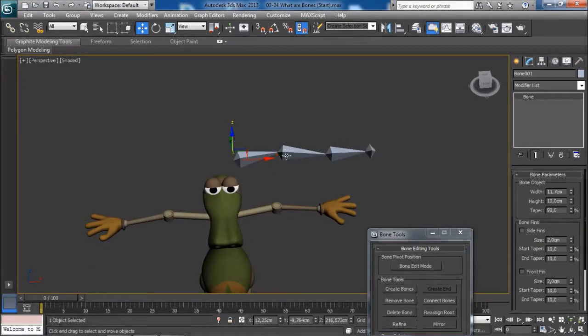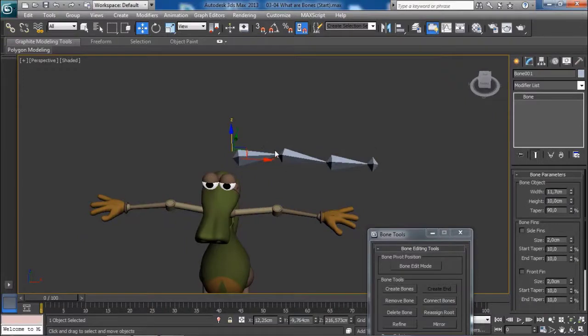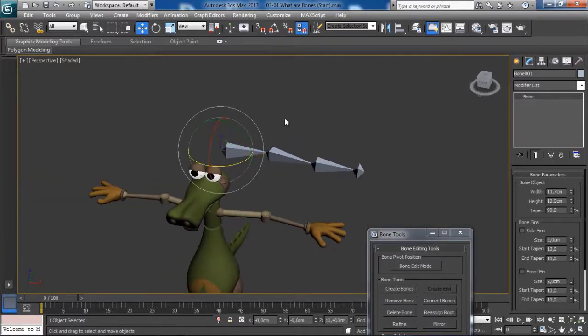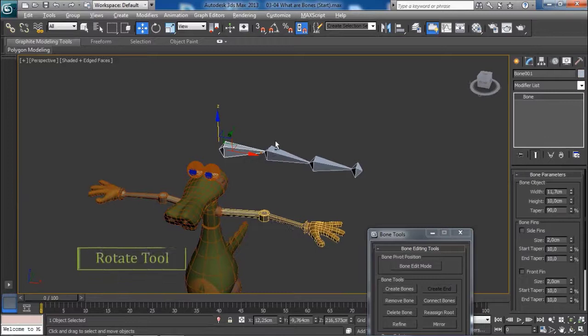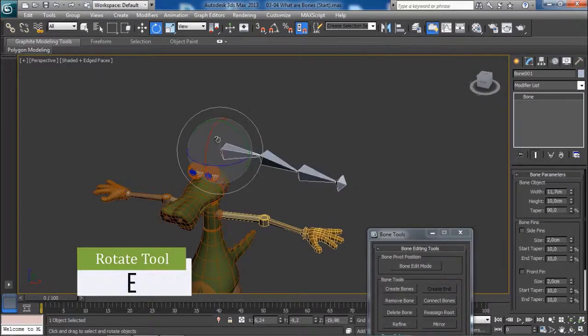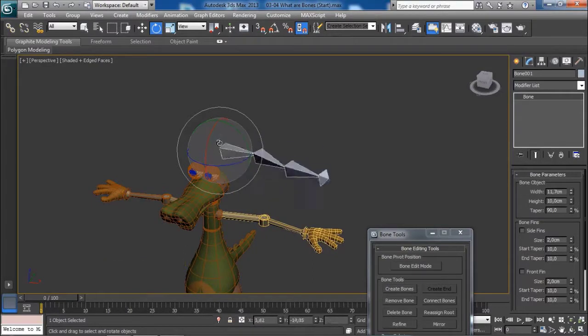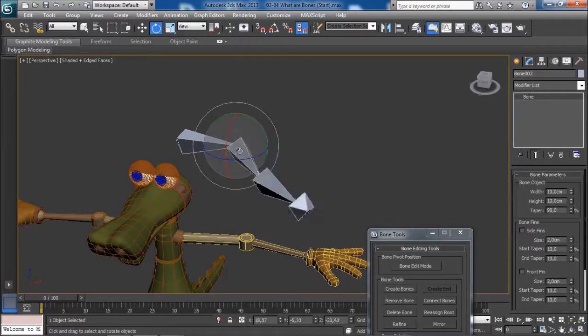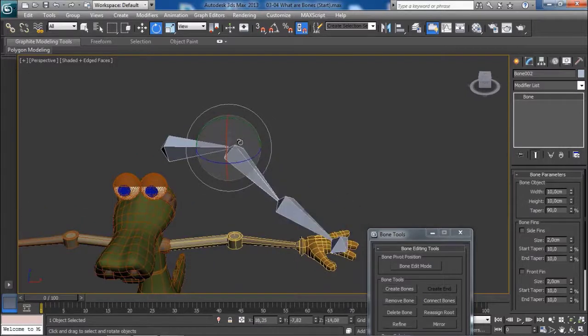I just want to show you how to adjust the size of your bone objects if you ever need to do so. Okay, great. So we have created now a bone chain. And notice, as we start to move these bones around, let's start with the upper bone, and as we start to rotate this, notice how we have created this automatic hierarchy, which is awesome. This saves us a lot of time. Go into the forearm. As we start to rotate that, all right, everything is working beautifully.